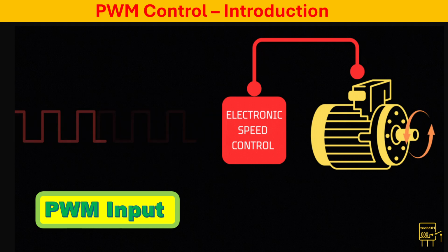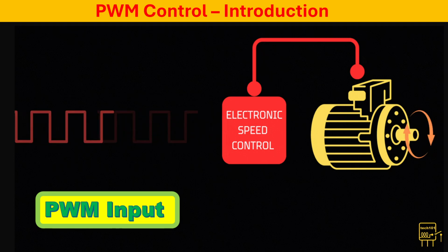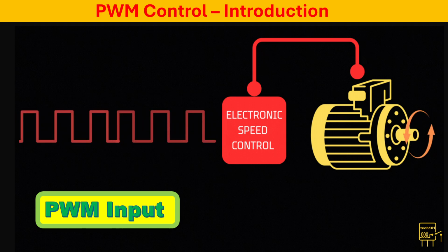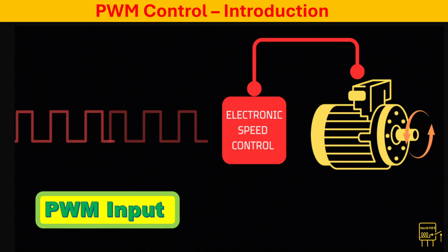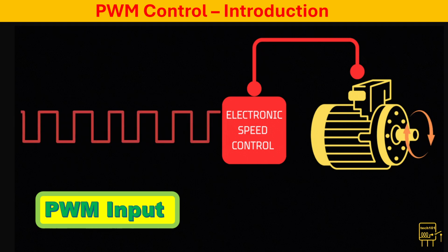Pulse width modulation, or PWM, is a technique used to control the amount of power delivered to an electrical device by rapidly switching the power supply on and off. Instead of providing a continuous analog voltage, PWM delivers a digital signal that alternates between on (high) and off (low) states. The key parameter is the duty cycle. By adjusting the duty cycle, you effectively control the average voltage and power supplied to the load. PWM is an efficient, precise control mechanism and widely used in dimmers, battery management, robotics, motor speed control, and industrial automation.